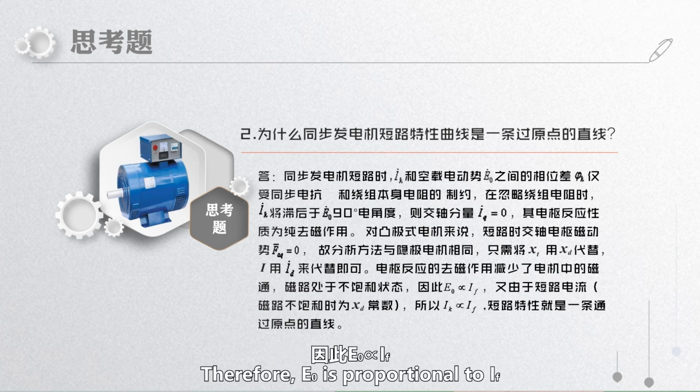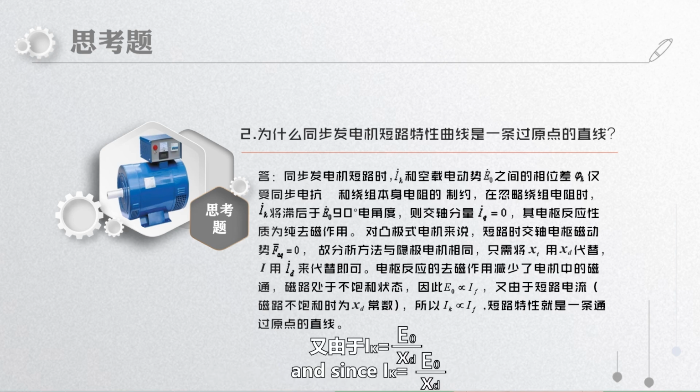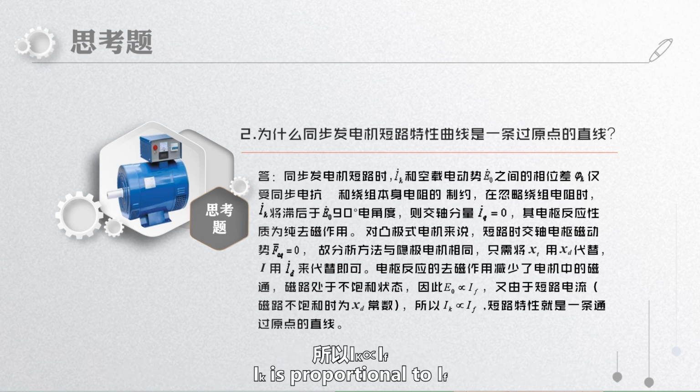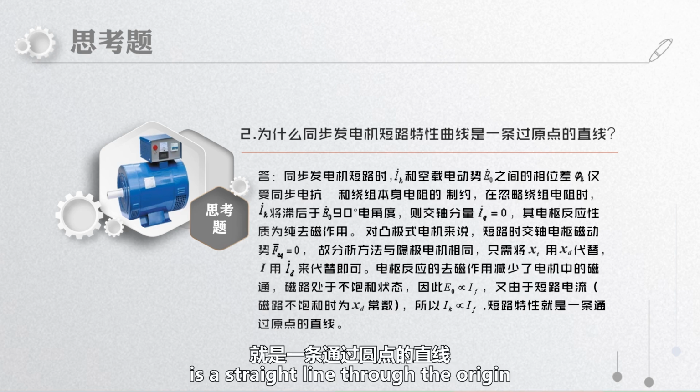Therefore, E0 is proportional to IF, and since IK equals E0 over XD, and the magnetic circuit is unsaturated and constant, IK is proportional to IF. The short circuit characteristic is a straight line through the origin.